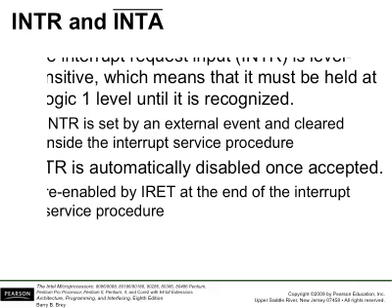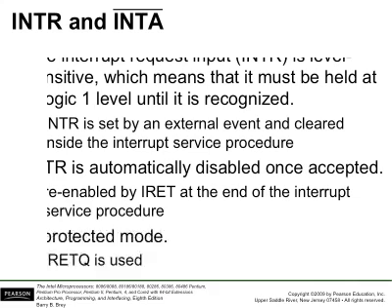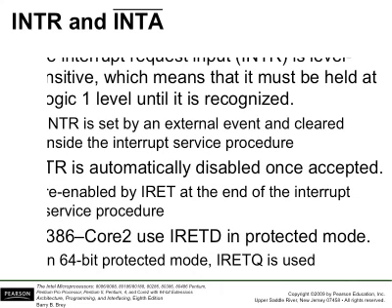Once the microprocessor accepts the interrupt, it will disable INTR, so there's not another one coming in. And it will enable this INTR pin after it returns from the interrupt service routine. For later processors, there's another interrupt return instruction, IRETD, that's used in protected mode.